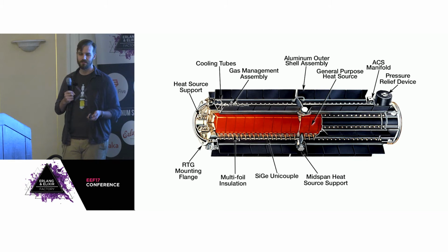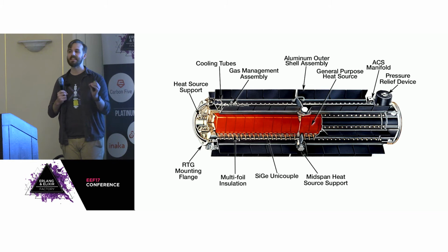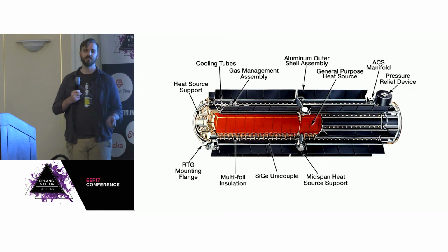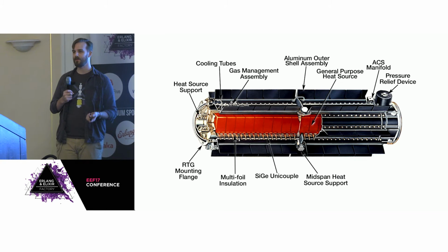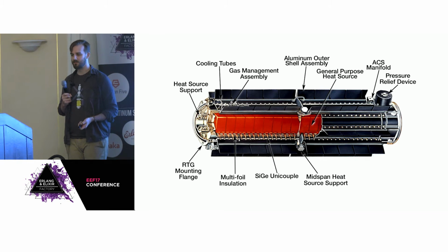Now, New Horizons, for instance, has a propulsion system with a little catalyst in the bed that has to be heated before you can turn the thing on. So they just bleed heat off of the tiny little nuclear reaction in the back of the spacecraft into the catalyst beds. Or if you have scientific equipment that has to be warmed up before you can open a shutter, same deal. So it's a tidy little self-contained system.